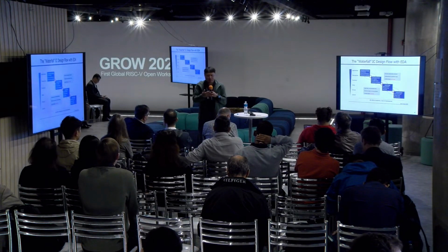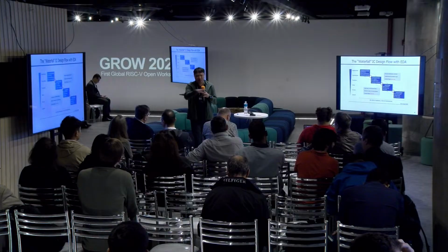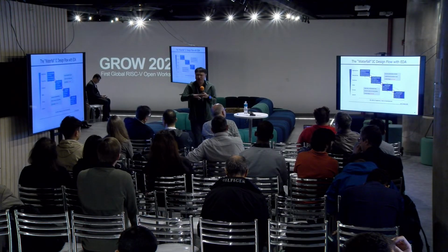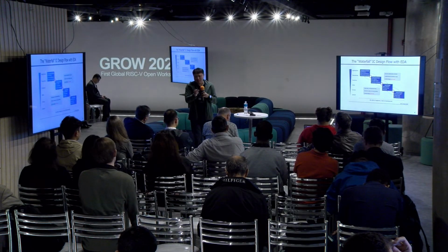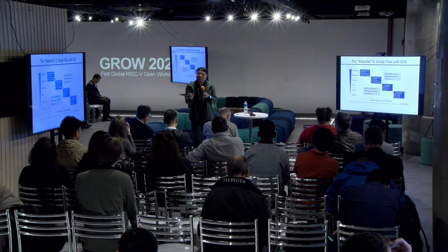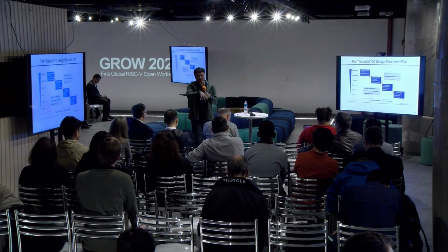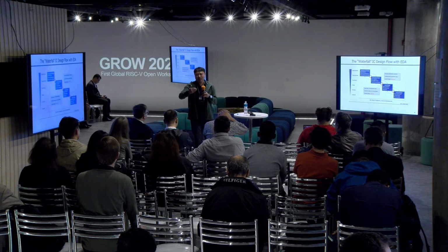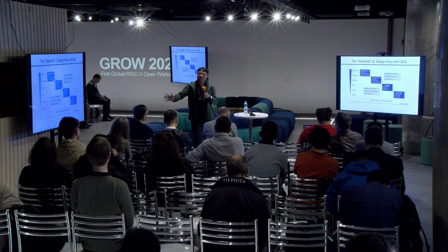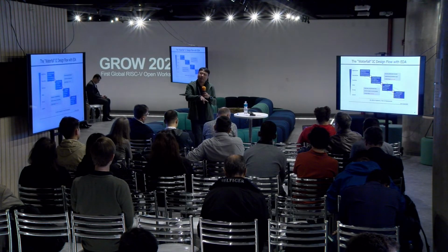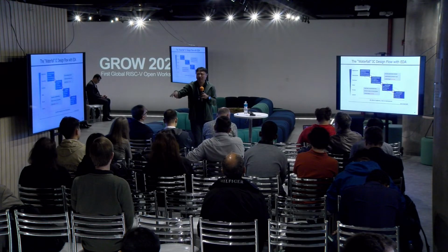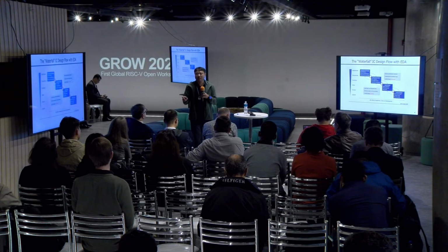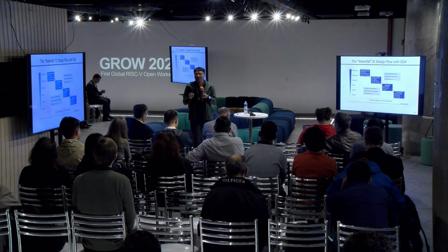But what I'm trying to say is, internally, as you said, in between different stages, you don't have to have everything holistic to learn together before you can start to use it. You can learn in between two neighboring stages, and you can still do a lot of work, right? For example, if you learn RTL and netlist aligned together, you can see that if I write RTL in this way, most likely it generates this kind of structure, and that is helpful for RTL optimization, right? Similarly, for mapping and placement, for every neighboring stage, if you can learn together, you can get some benefits. That's what I think.